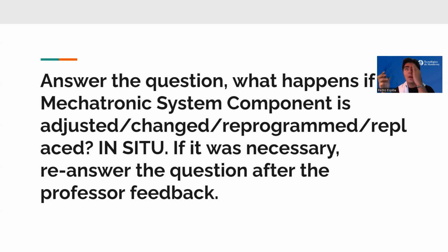It needs 24 volts to work, but the signal that it has to send has to be 110 volts, so the conversion is necessary. Now, with the LOGO, we send a signal so that when the ultrasonic sensor is activated, Q3 is activated, sending the signal to the 24 volt LED that receives the 24 volt signal, so the LED can turn on. One side is connected to the signal of Q3, and the other one is connected directly to the digital ground. So this is the way that the ultrasonic sensor works.